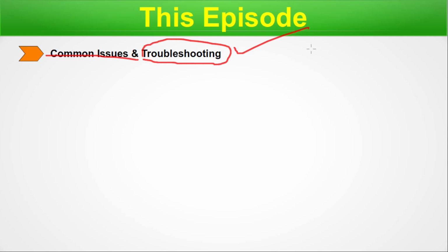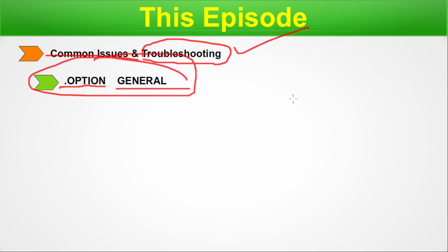Starting from this episode, we'll go into deep detail of multiple commands, and the associated issues are listed in a lookup table manner in this particular slide. So you get the details later, and you get the initial lookup table of what to do when, in this slide. Next, we will talk about .option general. We will focus on this particular command that is used inside spice.